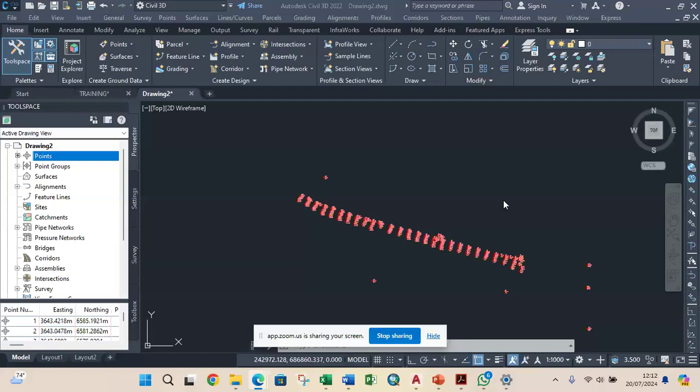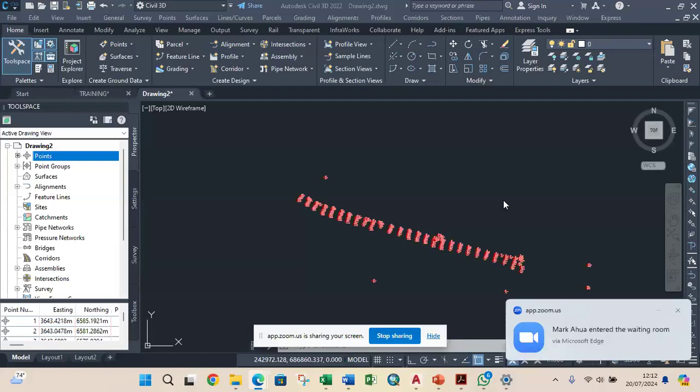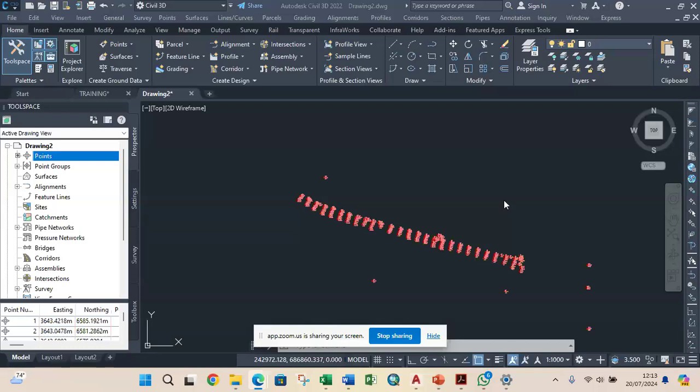So for me to check whether it's actually your reference now, know that most of us are not using the actual licensed software. So there are other tools you can use as well to check for your projection. We know Global Mapper and then GIS. So if I'm done with this, I can export it to Global Mapper and do a projection on Global Mapper. Then from there, I'll take it to a KML file and check on the location I'm working.